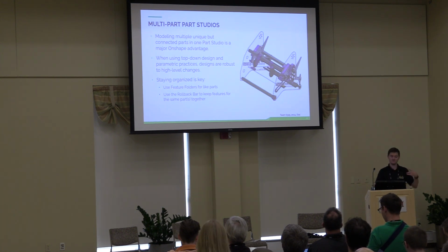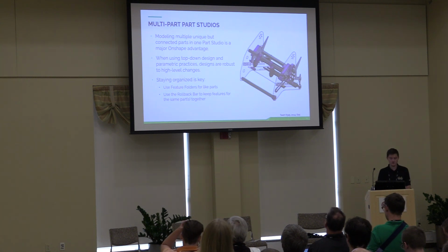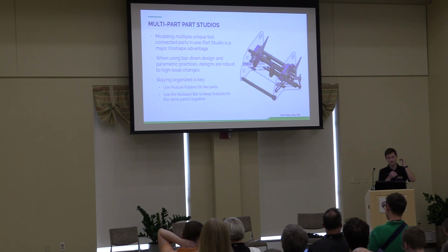But of course, the flip side to that is you are going to end up with a much busier feature tree because you're making so many more parts in one location. So staying organized is key. Make sure you use feature folders for parts and use the rollback bar to keep features for the same parts together. I'll demo that.